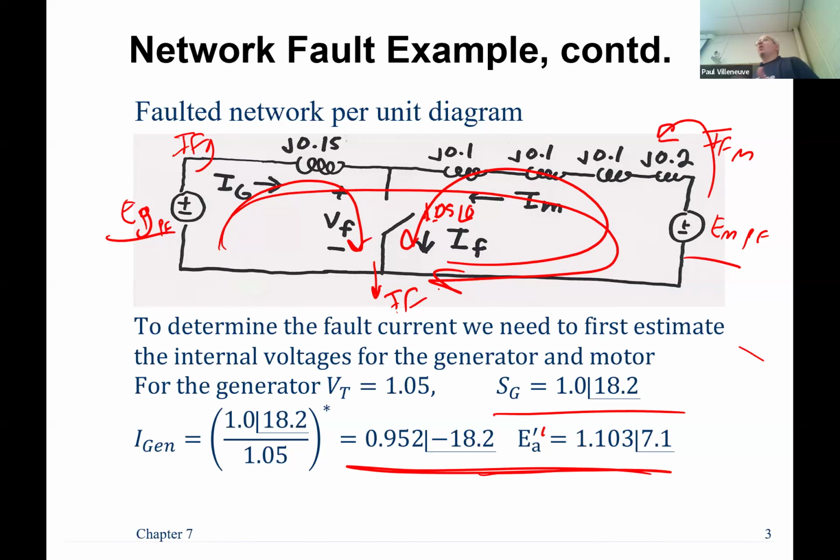Because all these generators, all these motors have protective devices on them saying, when there's a problem, go ahead and trip. But if I have some way of isolating that fault, whatever that way is, before either of these devices open, then they can stay connected, can't they? They can continue to operate the motor and still keep the system alive and well. Right? So what I need to do, it's called selective coordination.